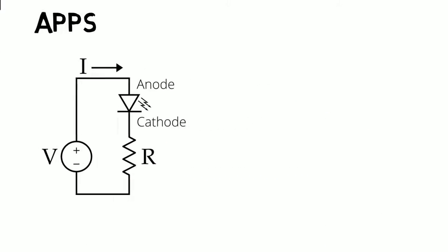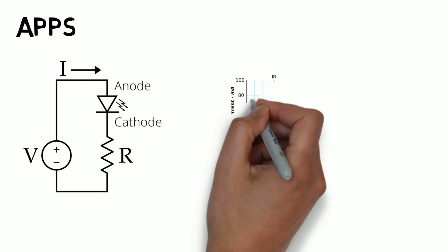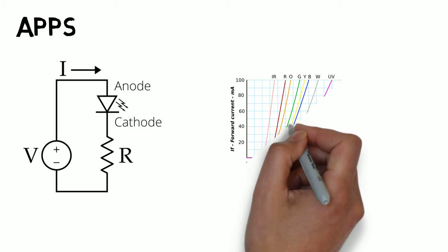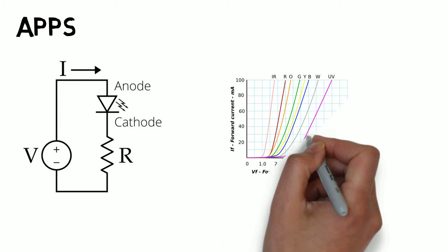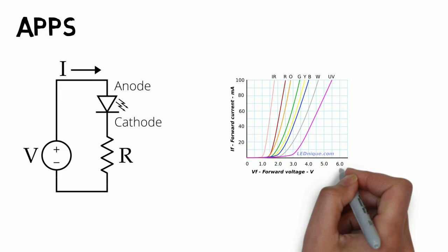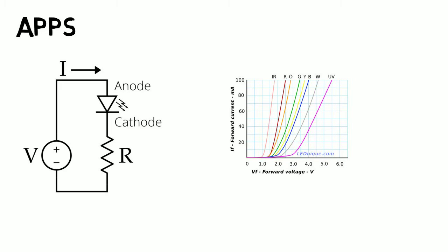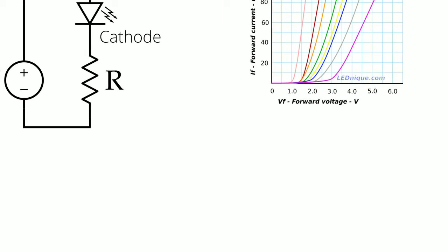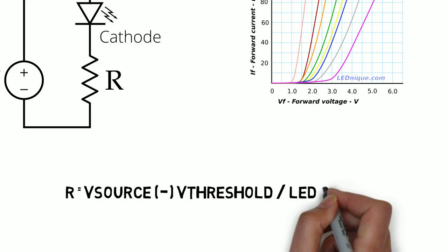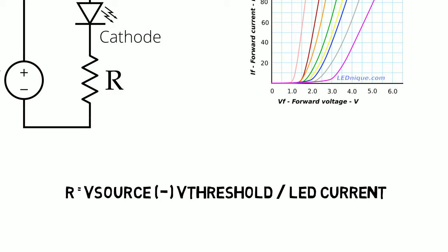Now, to keep things short and simple, an LED lights up only after reaching its threshold voltage value. This means for each millivolt after the threshold or knee voltage, the current draw of the LED increases exponentially. This eventually burns our LED, which is an unwanted effect. To prevent this, use this formula to calculate the required resistance to be used in series with your LED.